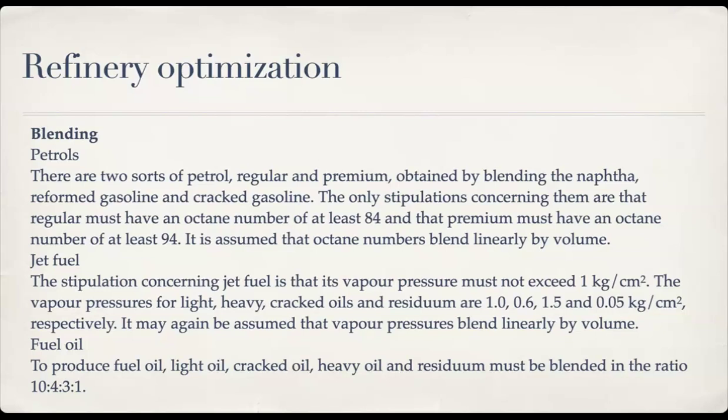Now we move to the next product, jet fuel. The stipulation concerning this product is vapor pressure. The vapor pressure must not exceed 1 kilogram per square centimeter. The vapor pressures for light oil, heavy oil, crack oil, and residue are 1.5, 0.6, 1.5, and 0.05 kilogram per square centimeter.